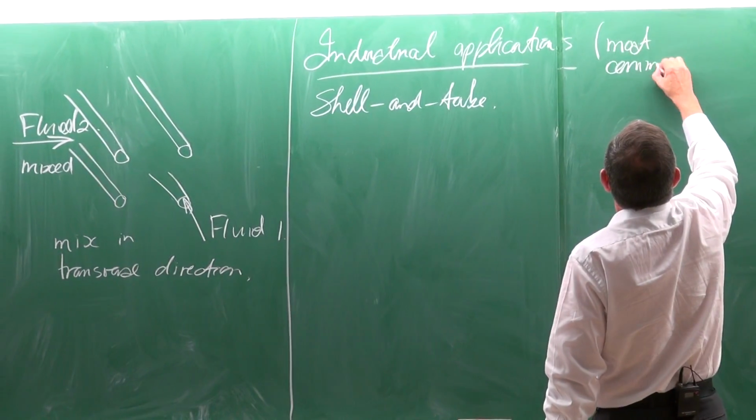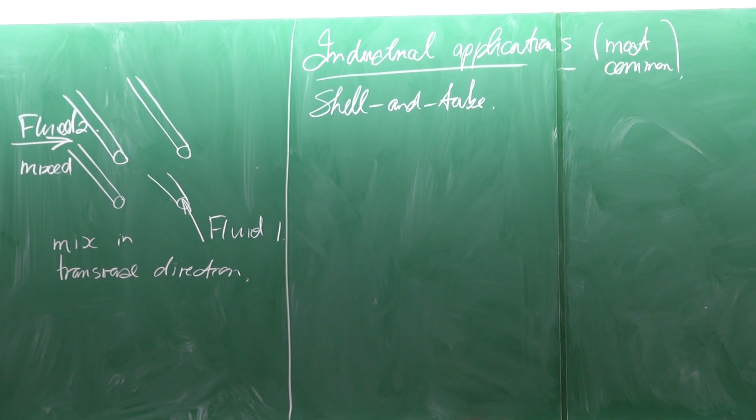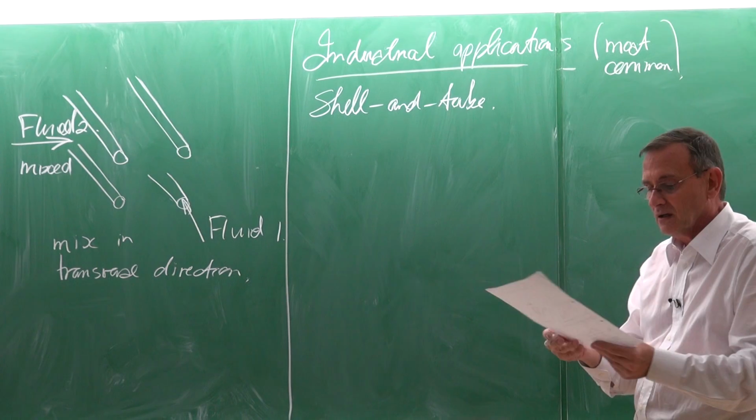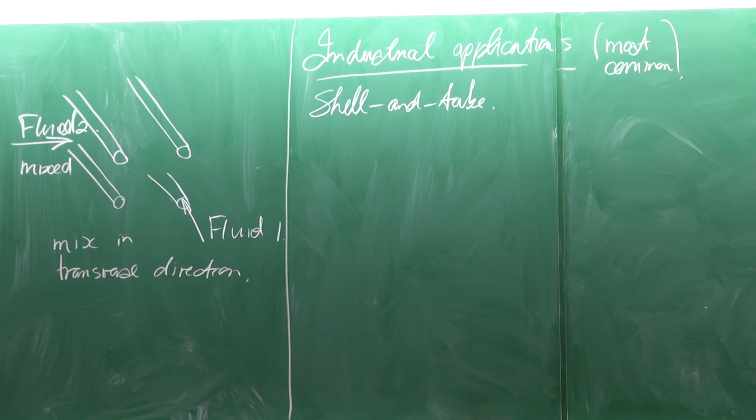But if I say that, then I mean that the heat transfer rates that we're talking of are normally in hundreds of kilowatts. So it's not the type of heat exchanger you're going to get into your car, in a fridge, the freezer, in a domestic or a commercial heat exchanger system. This is for hundreds of kilowatts. So for this building, for example, you will have a shell and tube type of heat exchanger, where the water which flows to all the units is being cooled in the shell and tube heat exchanger. So it is for big applications, normally very heavy. You also wouldn't get it on an aeroplane or anything like that.